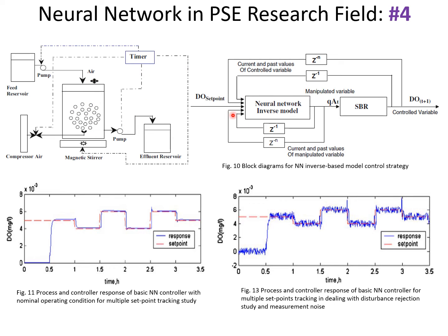So we use a neural network inverse. But this is a straight direct inverse model, one of the control strategies that we've taught you in our class, direct inverse model to control the SBR, which is quite a good method. Using again the inputs, the past inputs, that one minus is a past input, the past outputs, and of course the set point. Straightforward to manipulate the dissolved air coming in, to manipulate the DO of the process. Straightforward neural network control system.